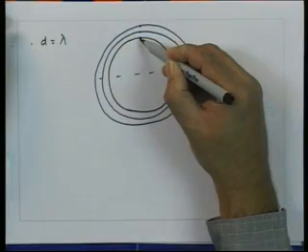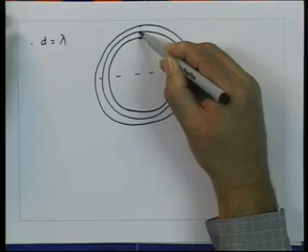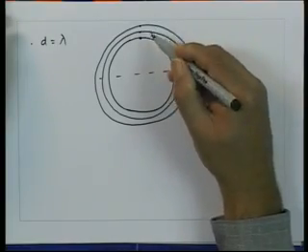What that means is, if I try to put a null corresponding to this value of psi, automatically there will be a null placed in this direction, which corresponds to this value of psi. So now I do not have independent control of every point on the radiation pattern. As soon as a certain point on the radiation pattern is defined, the other point on the radiation pattern is automatically defined.